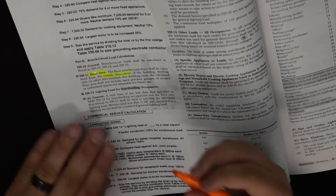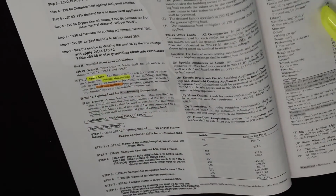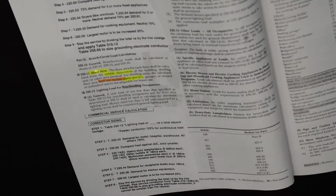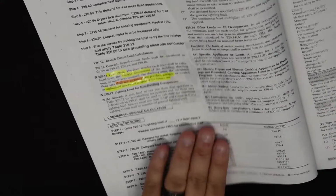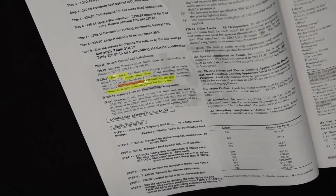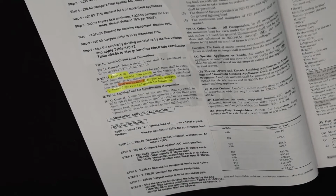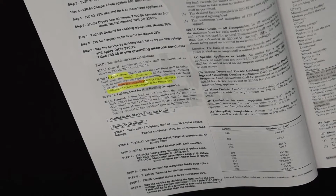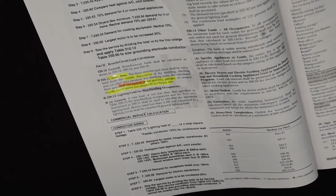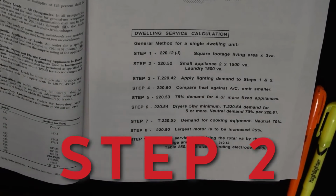The dwelling units, the calculated floor area shall not include, so dark color highlight shall not include open porches, garages, and then down at the bottom it says unfinished spaces not adaptable for future use. That's kind of important, because if you've got an unfinished basement, that's not what it's talking about, because you can finish that basement. But if you've got an old attic space that will never be used or never be finished, or something that will never be a finished space possible, that's what it's talking about. So we don't include porches, and we don't include garages, and we don't include spaces that can't be adapted for future use.